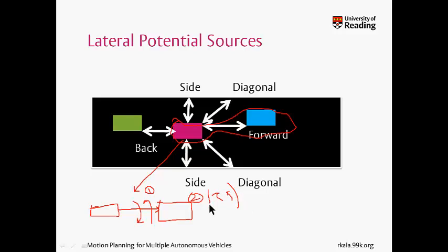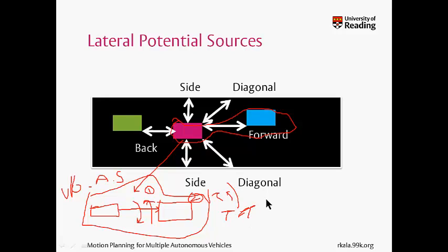So the first question is steering left or right, and the other is steering by which magnitude. Now, for the first question, for this very particular example where I'm only considering the forward direction, I say that steering clockwise or anti-clockwise, or steering left to right, is what I call an obstacle avoidance strategy or vehicle avoidance strategy, and I'll be talking about it in the next slide. So there's some strategy which gives me this magical sign, or this magical direction. The second is the magnitude, and I say my time to collision will denote the magnitude.